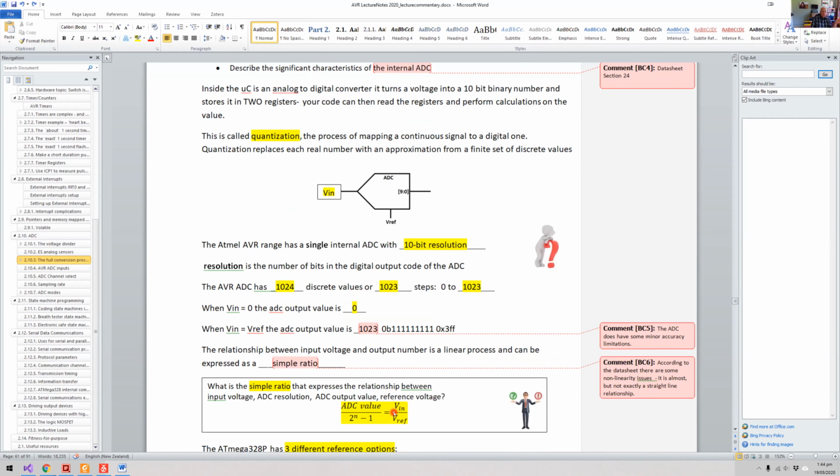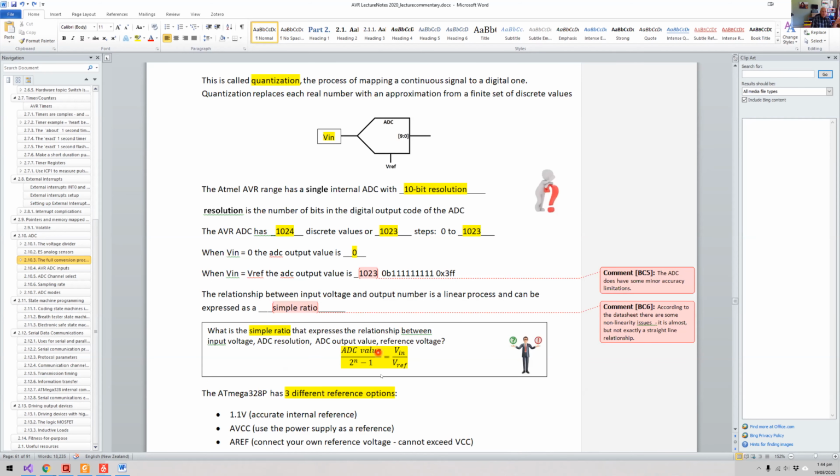So that means that when we're looking at this model for it, we can't just assume that this model will work for anything. It'll only work within the range of the ADC and within the range of the voltage with reference to this voltage reference. So what does that mean in terms of this relationship here?